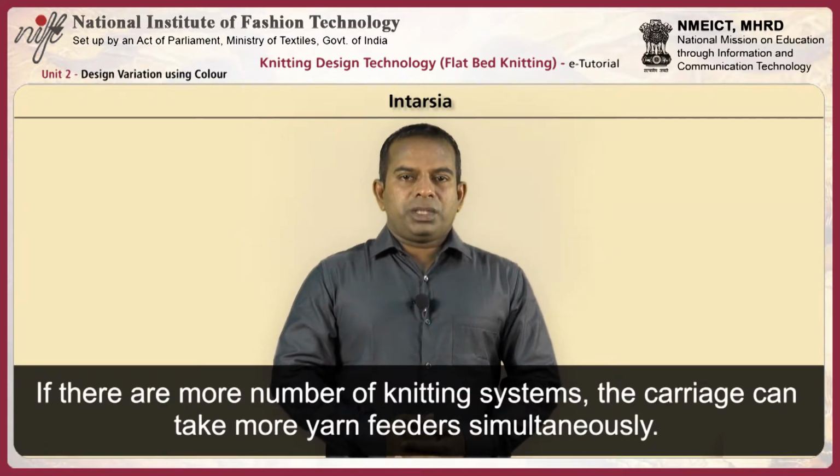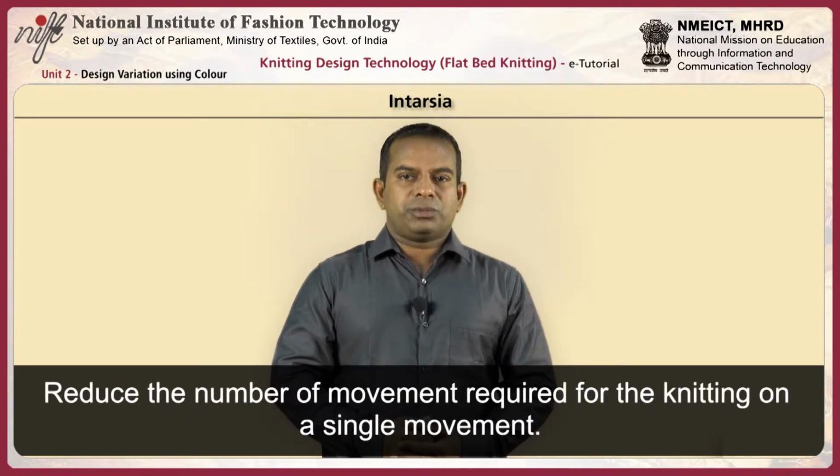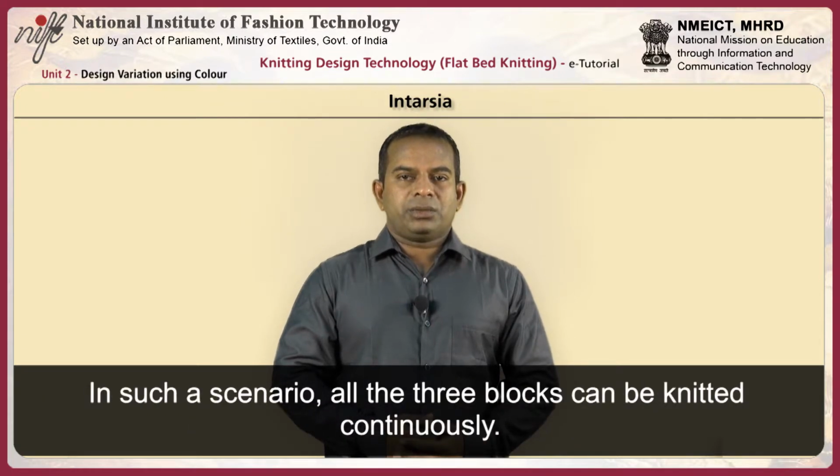If there are more number of knitting systems, the carriage can take more yarn feeders simultaneously and reduce the number of movements required for the knitting. Alternatively, if there are feeders available with a kickback system, it will allow the feeders to kick sideways and go up, clearing the knitting needle to perform without any worry of clashing with the feeder. In such a scenario, all the 3 blocks can be knitted simultaneously.